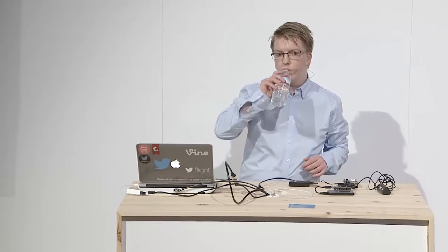The other thing, though, is that this is cheating. This device is not tweeting. In fact, really, this device is just a trigger. This device is connecting to the microphone on my phone, getting information back from the microphone about how loud it is, and then triggering through Bluetooth the Twitter app on my phone to tweet for me. Now, actually, this is very, very common. If you're building this kind of thing with a small embedded device, you're very often not going to find a device which has got the memory capacity or the ability to do complex things like OAuth, okay?